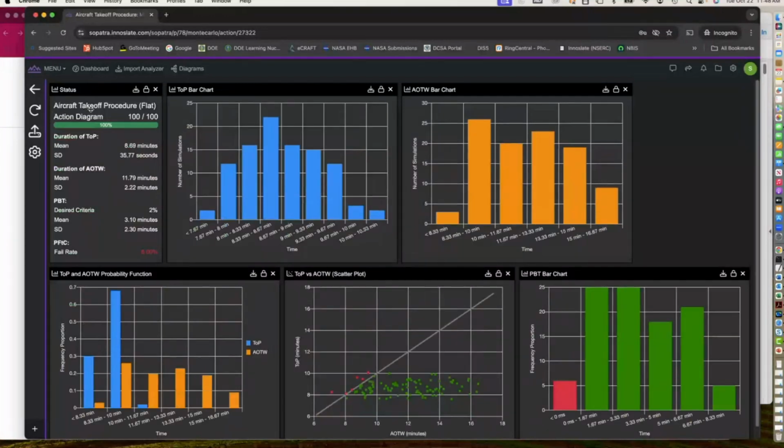And so you can see what we get. The fail rate came out to 6% in this case. This is why you want to run a lot of iterations, by the way. You want to refine it and get a better number with the longer time. The more complex it is, the more iterations you need. Probably for something this complex, I'd run 10,000 at least to look at it. But that takes too long to do in a demo.